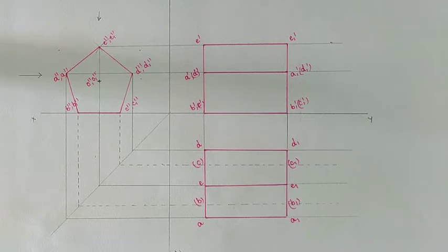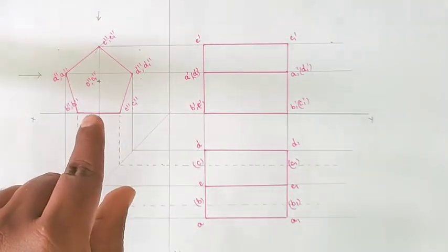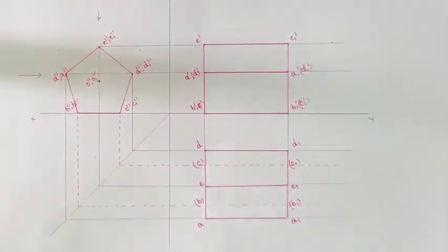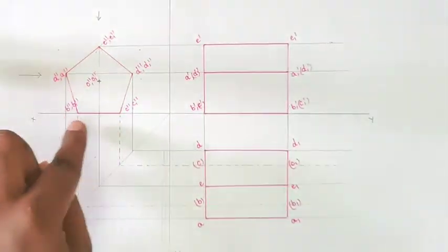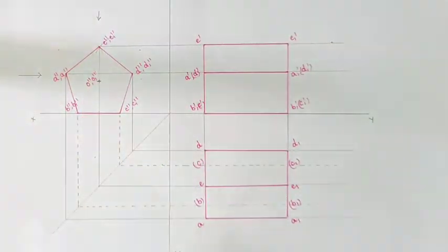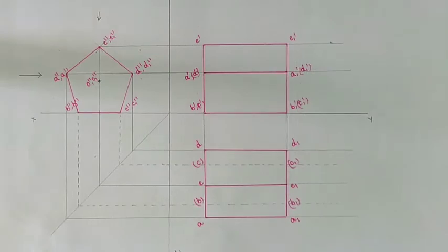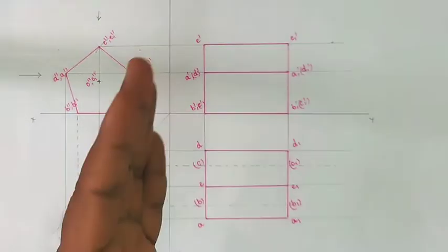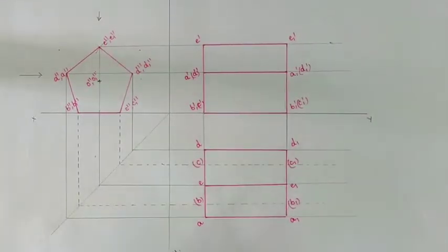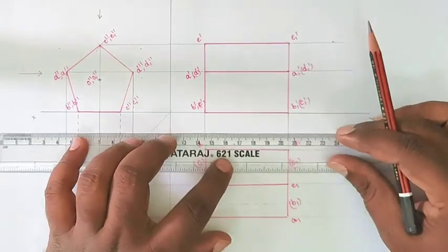So how will we draw the side view of our diagram? When the rectangle face is on the HP, we will first of all draw the side view on the reference line. After that we will construct the front view from the side view. After constructing the side view, by projecting the horizontal and vertical projection lines and drawing the mitre line, we will get both the front view and the top view of our diagram like that. After that we will give the notation.